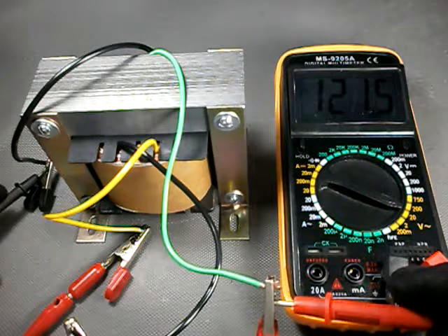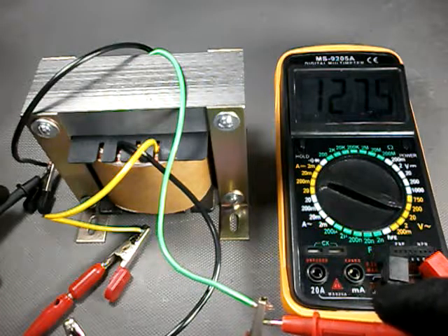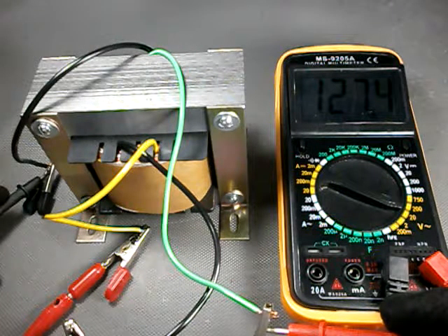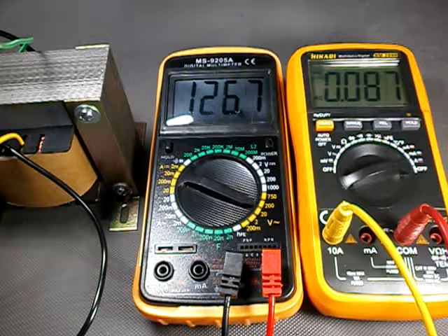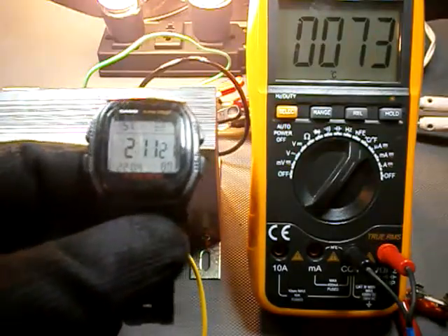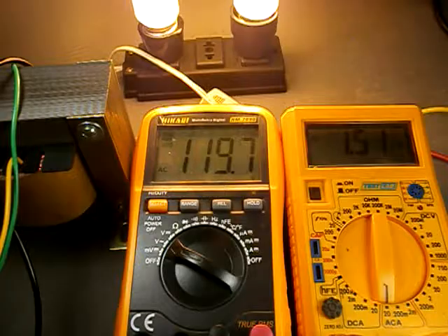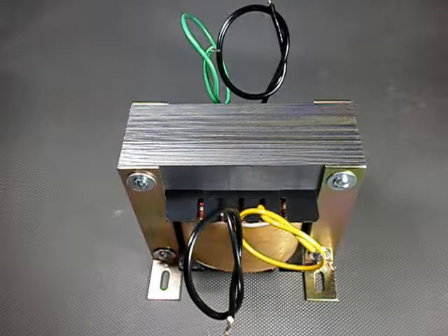The basic tests we performed in our last video showed that the transformer is delivering the right voltage on the secondary, is drawing a low idle current in the primary, is not overheating and has a better than predicted regulation. For applications like our isolation transformer and for most linear power supplies, this is enough to guarantee that the transformer we built is okay for operation.